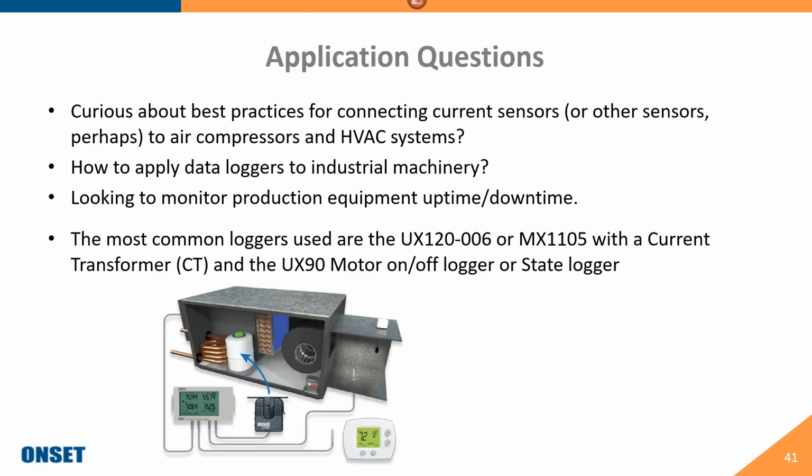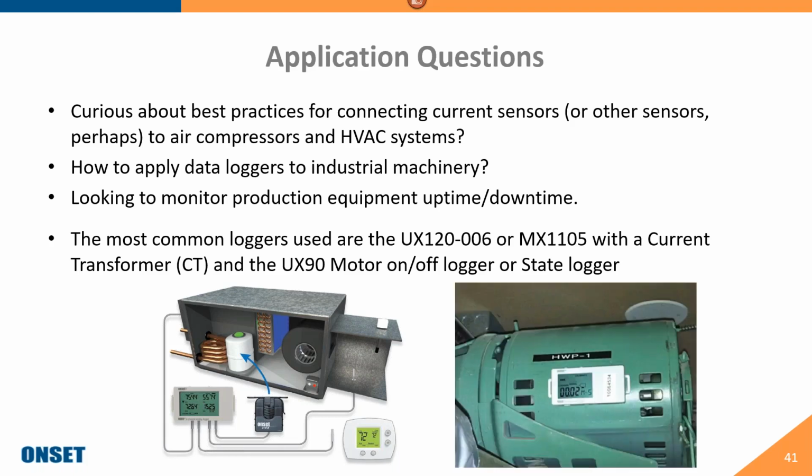And then for the runtime, here's an example of looking at an HVAC. You can monitor amperage to get an approximation of, one, what is it pulling for amp draw, but two, how often is it running? And then you can also look at your intake and outtake temperatures and your temperature near the thermostat. And then I think I swiped this image from Shannon earlier of just looking at a motor housing.